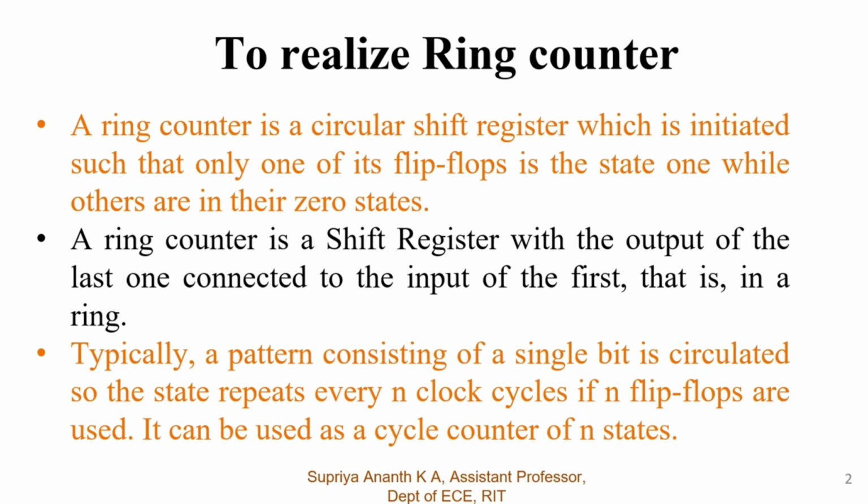The experiment is to realize the ring counter. Generally, a ring counter is a circular shift register which is initiated such that only one of its flip-flops or latches is at one state, while the remaining values will remain zero. That is nothing but a zero state.